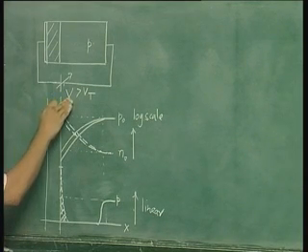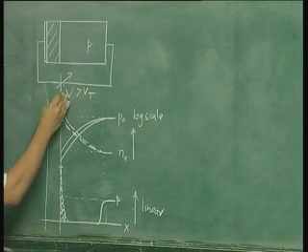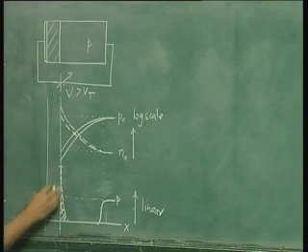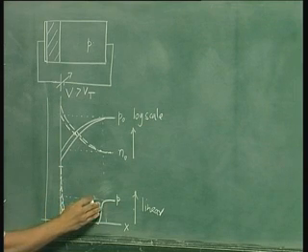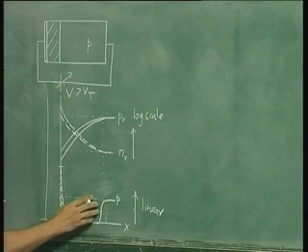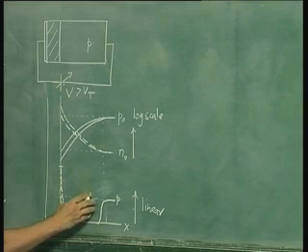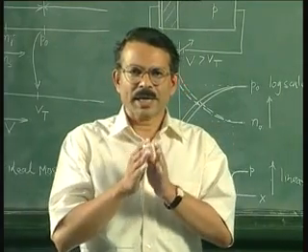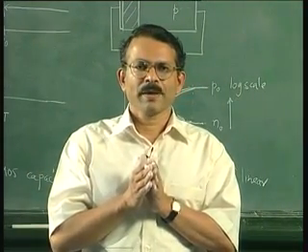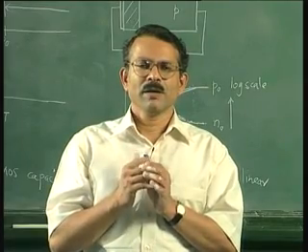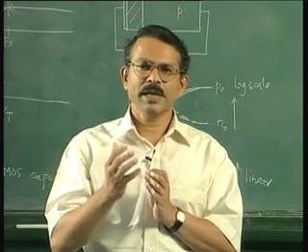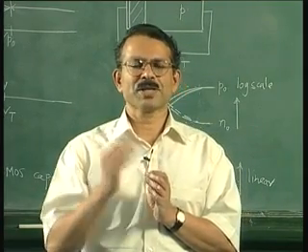Therefore, whenever you apply extra voltage, you need extra charge in the semiconductor. Beyond threshold, the extra charge comes more easily from the electrons rather than by depleting the holes and exposing the negatively charged acceptor impurities. So until the capacitor reaches the threshold, when you increase the voltage, the extra negative charge required in the semiconductor comes from the ionized impurities by expanding the depletion layer.